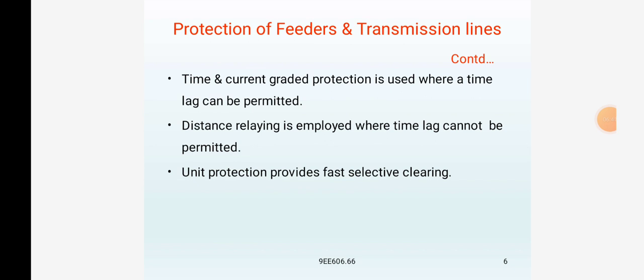And the causes for bus bar faults: bus bar faults are generally single line to ground faults. The following are a few causes: failure of support insulators resulting in earth faults, flashover across support insulators during overvoltages, heavily polluted insulators causing flashover, failure of connected equipment, and lastly, earthquakes, mechanical damage, etc.